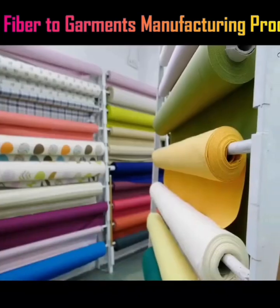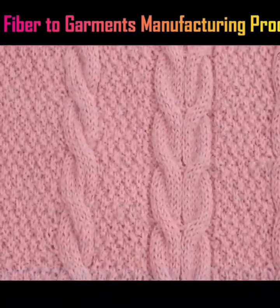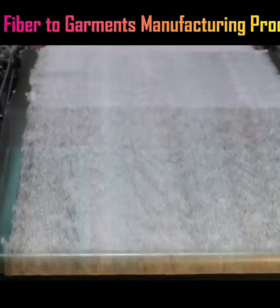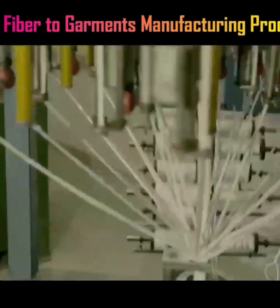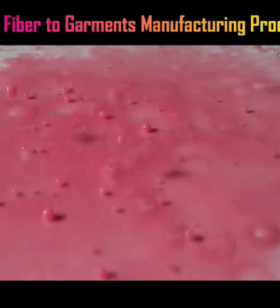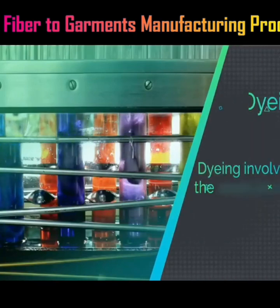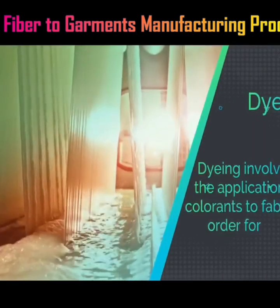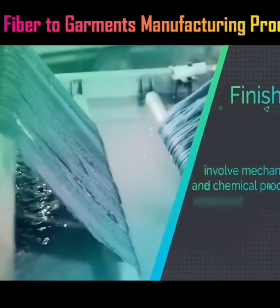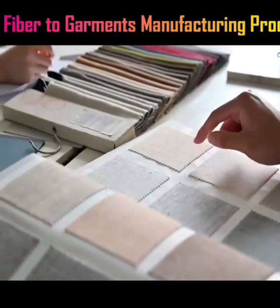Fabric is a plain sheet of cloth which is made by a weaving or knitting process. Most fabrics are knitted or woven, but some are produced by non-woven processes such as braiding, felting, twisting, etc. Wet processing. Fabric wet processing is a process used for dyeing and finishing the fabrics. Dyeing involves the application of colorants to fabric in order for it to become colored. Finishing may involve mechanical and chemical processes employed commercially to improve the acceptability of the product.